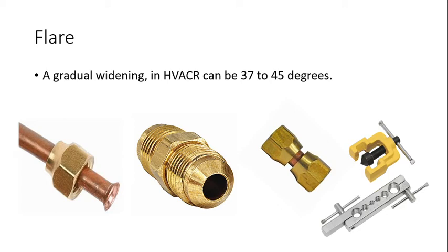Flare. Flare is a gradual widening. In heating and air conditioning, it's usually between 37 and 45 degree flare depending on the manufacturer of the fittings or the equipment.